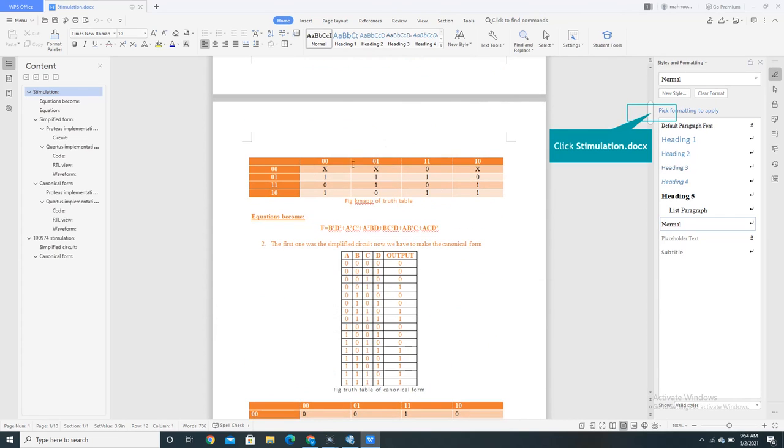From the K-map that is created over here, I would be creating 4 input boxes. So if we take these 2 as inputs, for example, I would get B positive, since in this both B is positive, and then for this both C bar D, and this is present over here. Just like this, I would be creating the mapping and adding it up, and this equation would be formed.